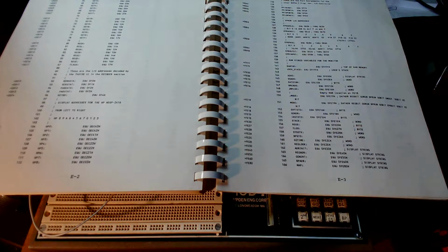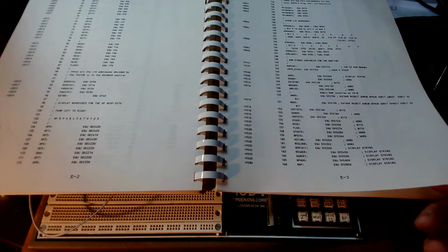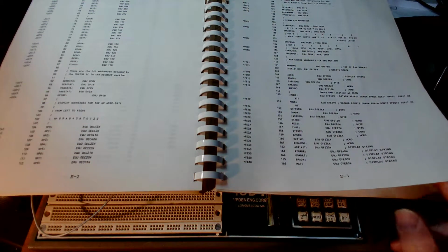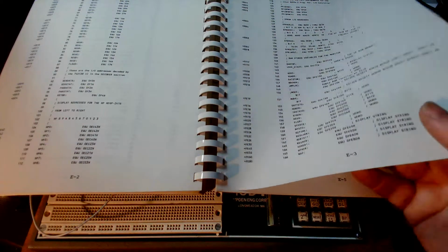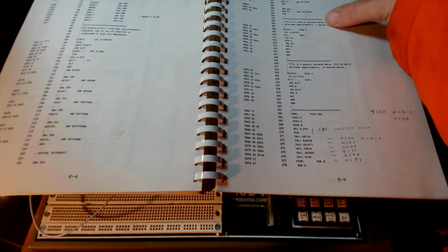it was pretty obvious that it didn't match very well, right? So all the addresses were of course different, also the programming was a little bit different, but the overall structure of the monitor program between the MCB-1 and the MCB-1A successor, which is the ROM listing here, were sufficiently close so that I could then use the annotations and the comments in this MCB-1A ROM listing to figure out and identify the corresponding routines and their addresses and the calling conventions for my MCB-1.